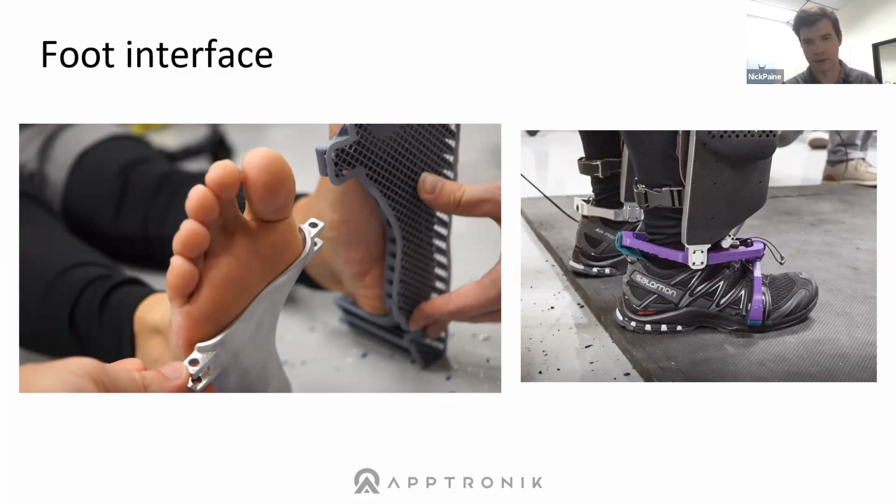And the reason for that approach was to try to minimize the relative motion between the human's skeleton and the exoskeleton structure. We also included force sensors in between the human and the structure of the system, but that is one of the implementation challenges with this approach, is finding quality force sensors for those embedded foot applications. The next system that we designed used a different strategy here, and I can talk about that if we've got time.